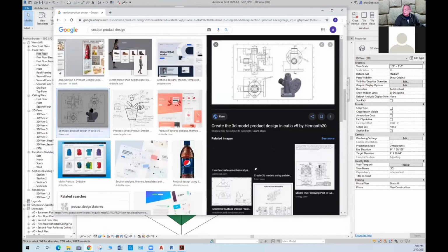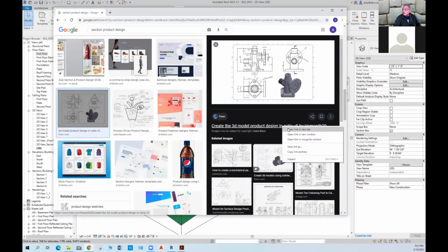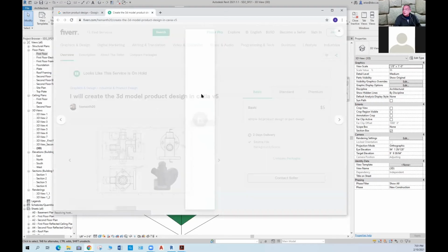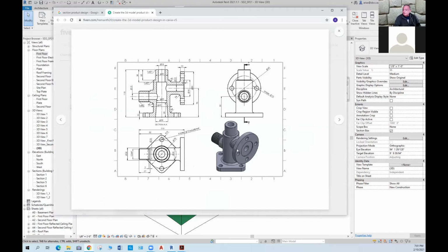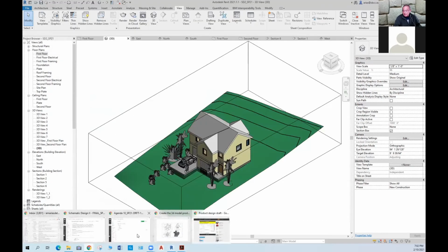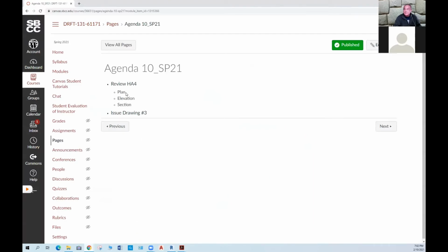And so once again, you can see here also a 3D object. Then we see the top view, similar to a plan view. And this is third angle orthographic projection in Europe, first angle, sorry. Section view of the object and an elevation view of the object. So it's important to remember then that all of these views that we're talking about in our homework are orthographic projections. That's the idea, right?